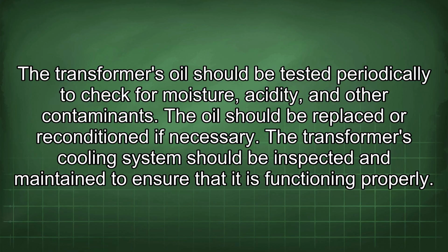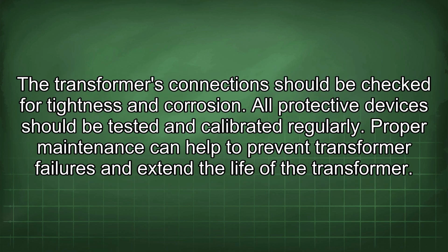The transformer's cooling system should be inspected and maintained to ensure that it is functioning properly. The transformer's connections should be checked for tightness and corrosion. All protective devices should be tested and calibrated regularly. Proper maintenance can help to prevent transformer failures and extend the life of the transformer.